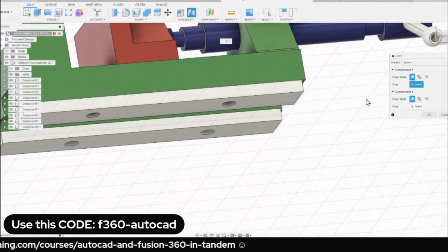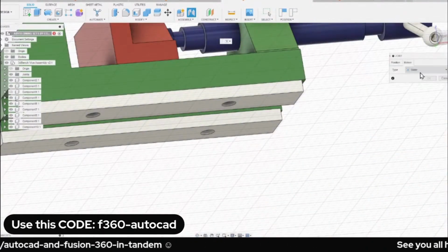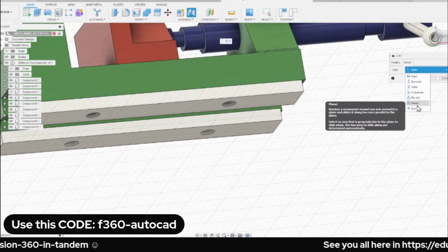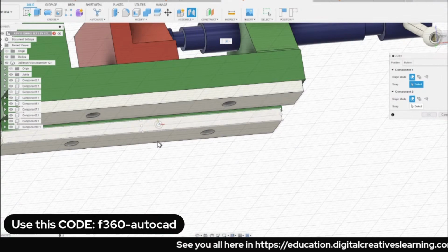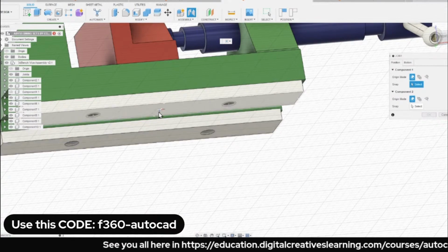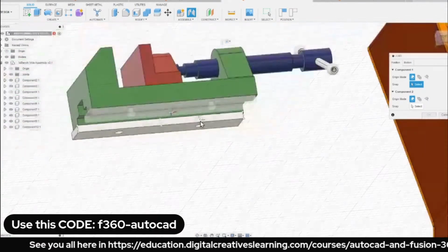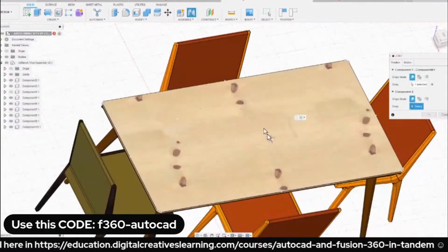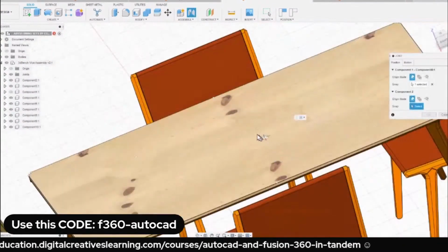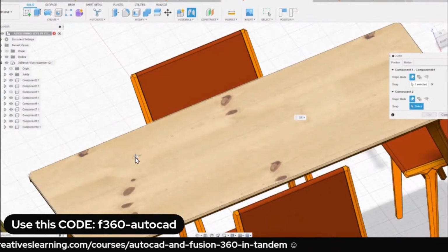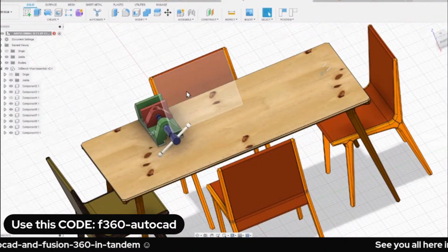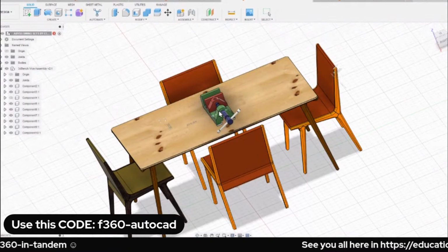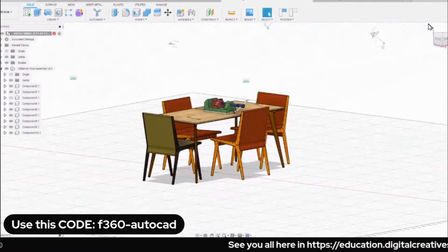So hitting J, motion type definitely would be planar, diba? Planar. So selecting any of this joint origins, I prefer this one. Going to our tabletop. Oh, how about this? Selecting this joint origin. So selecting OK. It's now on top of that table.